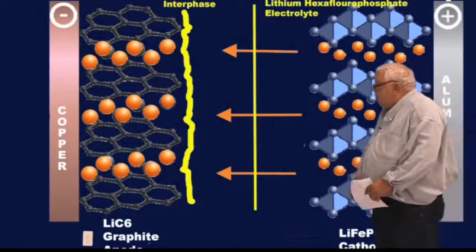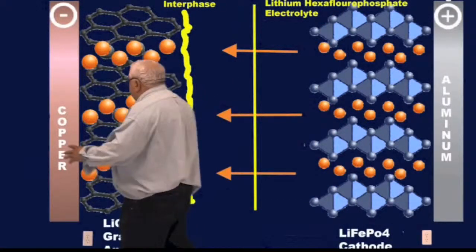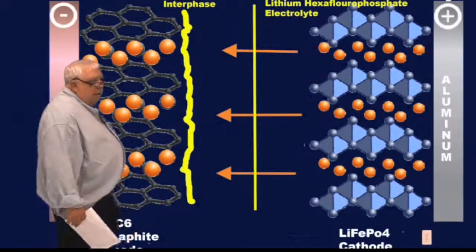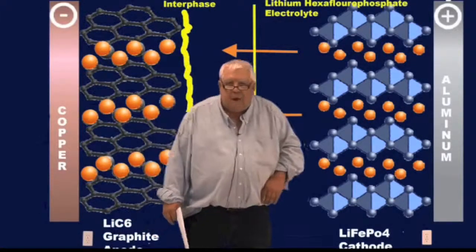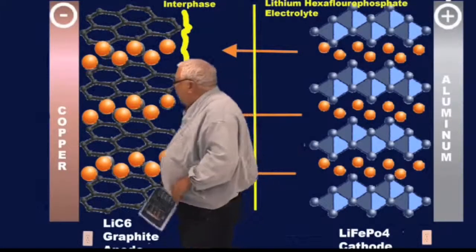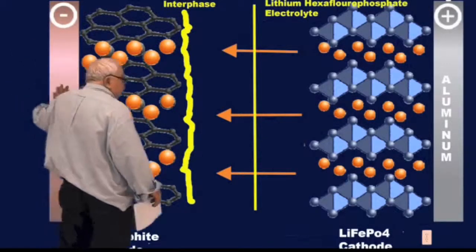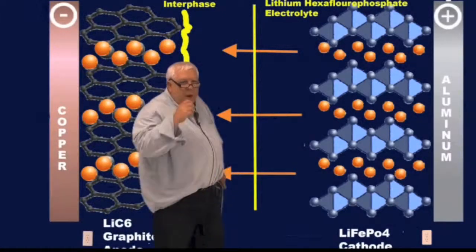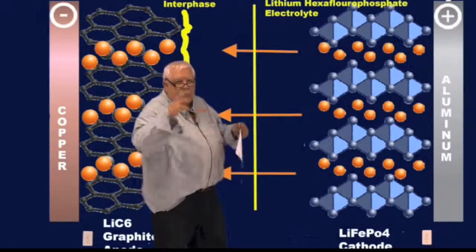When we discharge the battery, we hook through a load, and there's just a huge difference in potential here. We have a lot of negative charge built up, not on the plate, the copper plate like a capacitor. Yes, they do build up there. And you do have kind of a capacitive effect, but that wouldn't provide us very much energy. Much more so, we have this fuzzy area, this thick charcoal wall with billions of lithium ions intercalated into that structure.